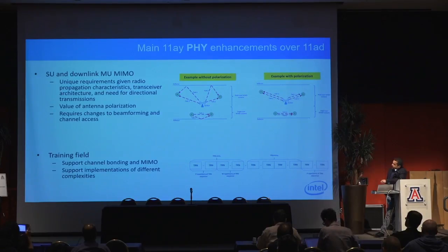There has been a lot of improvement to be able to do MIMO, to be able to do training, to be able to find these paths. There have been a lot of improvements on how the training is done. How do you sound the channel, so that you can actually find channels that have good properties, so they're not really correlated, so that you can really do MIMO.